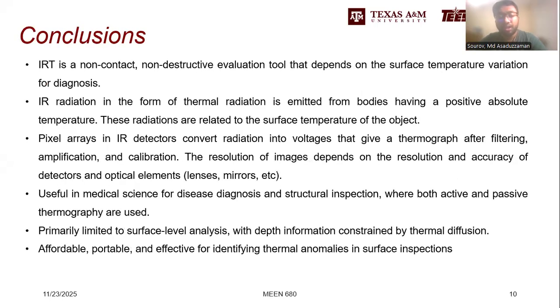To conclude, infrared thermography can be called a versatile, non-contact, and non-destructive technique that converts emitted infrared radiation into meaningful thermal images. Its effectiveness depends on the camera's optical components, detector sensitivity, and proper calibration.